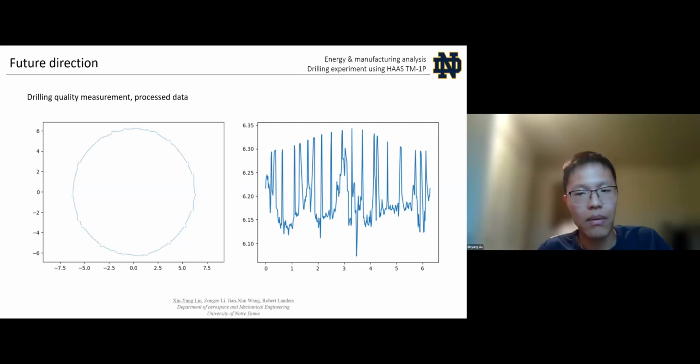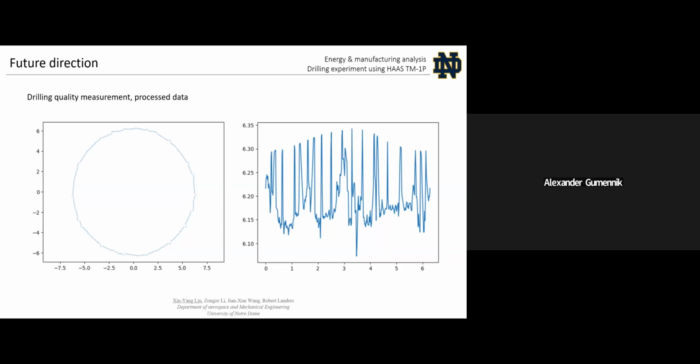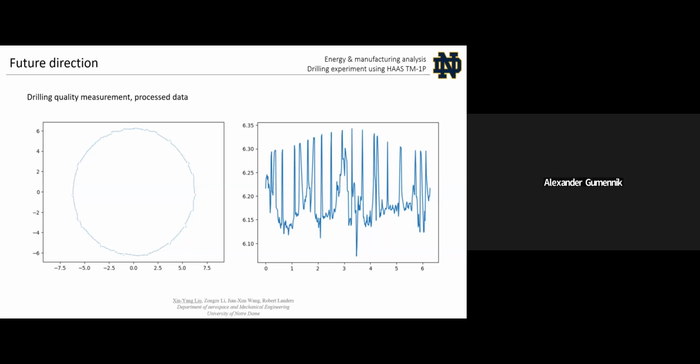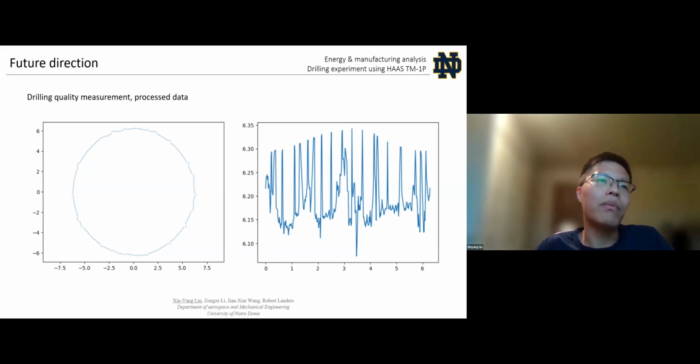Yeah. Which means to me that you have a distortion in the measurement, where your whole circle is basically squeezed in one direction. And it cannot be due to the drill, because the drill will make a perfectly round hole. So you do have some imperfection. You have a systematic error in the way you measure that. Yeah, but we're not sure if the measurement introduced the systematic error or if it was introduced by the drilling process. So, yeah.